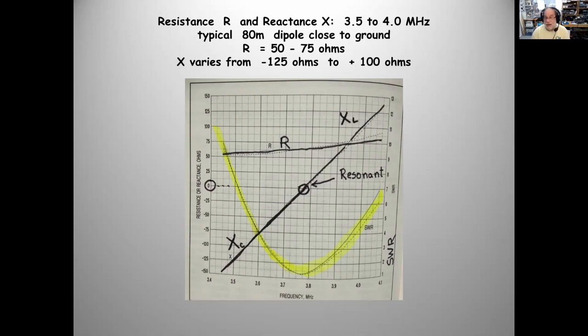So in order to correct this, what do I need to think in my shack? What do I want to make closer to the 50 ohm value? I want to change it so the reactance becomes 0. I want to cancel the reactance. Grampy, you're not pushing at the right time. Well, I can't literally yell up to my antenna. So what can I do? What do I put in my shack that can cancel the reactance at the antenna?